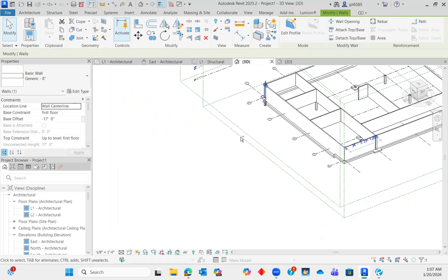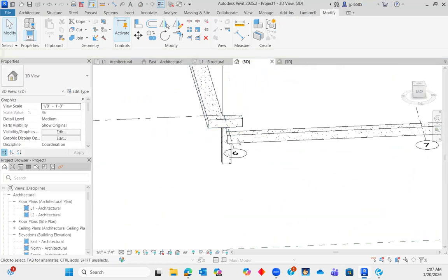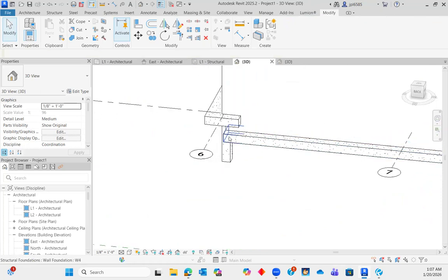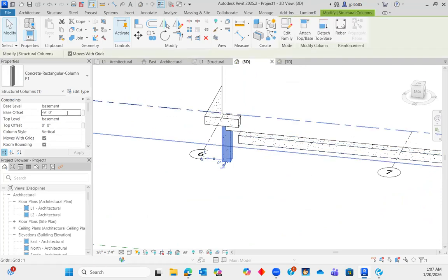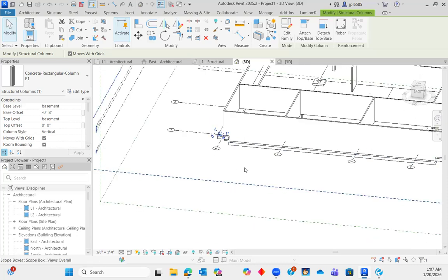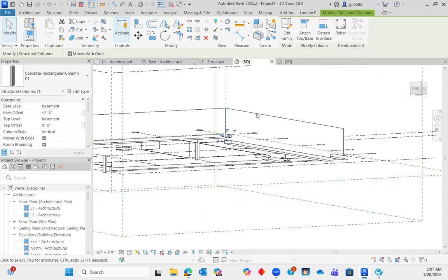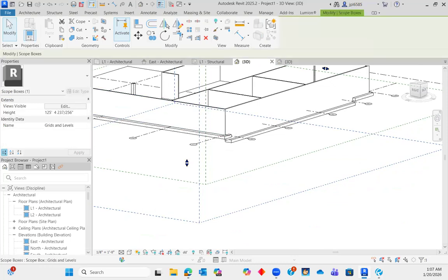It's going to not let me select it. There, and you can just delete it. And that's just the pier, actually. I'm going to fix that, or wherever that belongs. And then you can see I have the footing step in there if there needs to be a footing step, if they're supposed to be at the same depth. This depth is at -17, so -3 feet below.